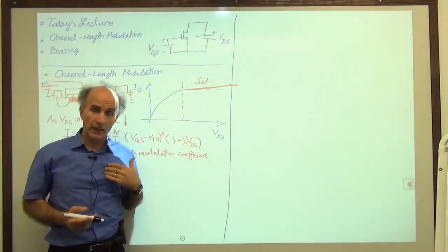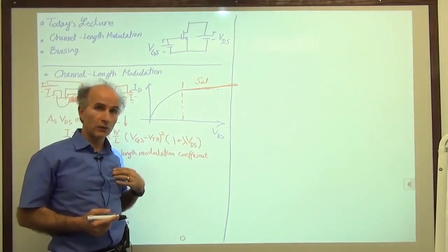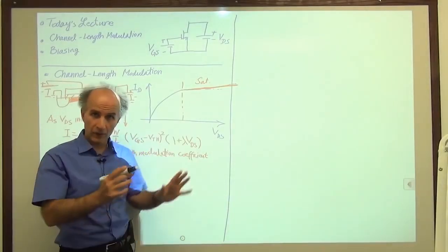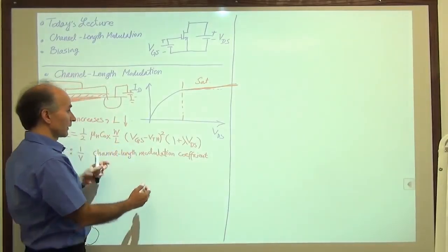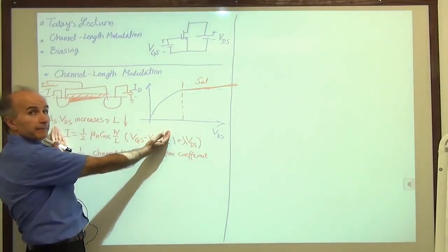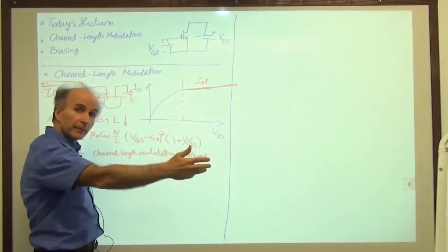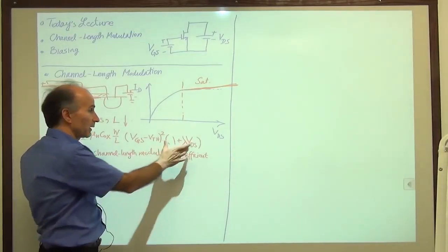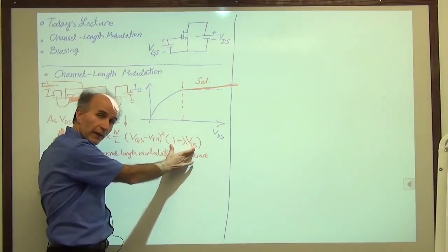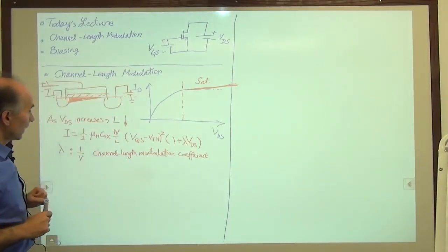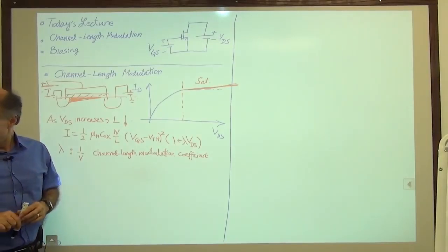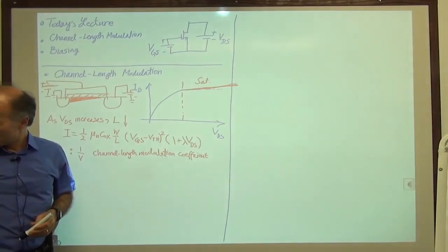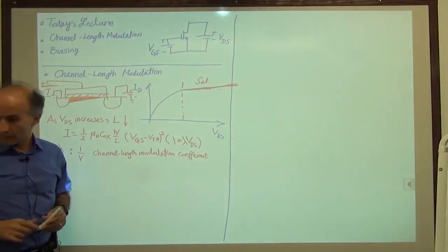So as engineers, our first reaction should be to use the simplest model possible. When I see a MOS device, and I know by some calculations that it's in saturation, the only thing I consider is first this, right? And then I go along and see where I end up. If the results are not very sensible, then I have to trace back and say, well, maybe channel length modulation is important, so I should include that. Okay? All right. So with channel length modulation, we have this behavior for the device. And let me see if there's anything else I want to mention about this.